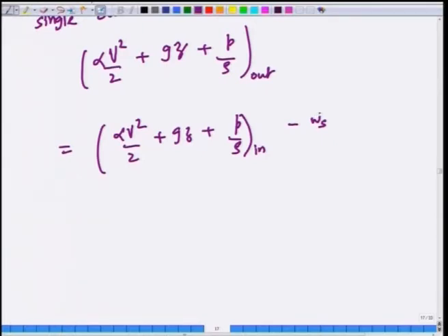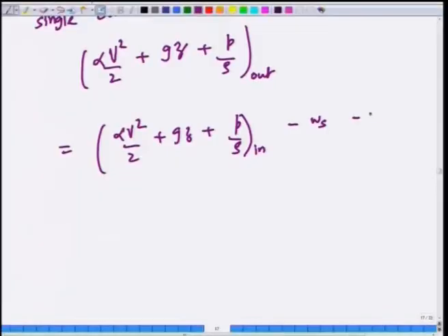So, we took the convention that work done by the CV on the surroundings is positive, and work done by the surroundings on the CV is negative. So if Ws is positive, that means work has been extracted out of the CV. If Ws is negative, then work is being put into the CV, minus the viscous losses. The viscous losses are always positive, WL is always greater than 0.